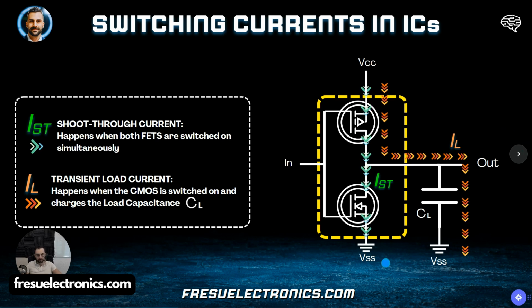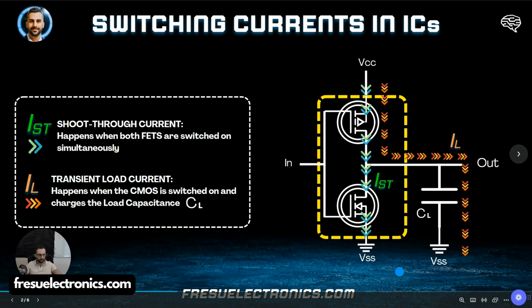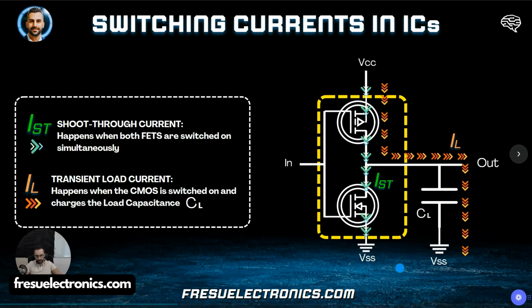For example, for processors, FPGAs, and microcontrollers that have a large number of logic gates switching within, the shoot-through current will be more prominent. If we have instead some other IC where a large number of pins are used as input and output and connected also to external loads, then the transient load current will be more prominent. If you really want to go a little deeper into this topic, you can check the books from Archambault and also from Ott.